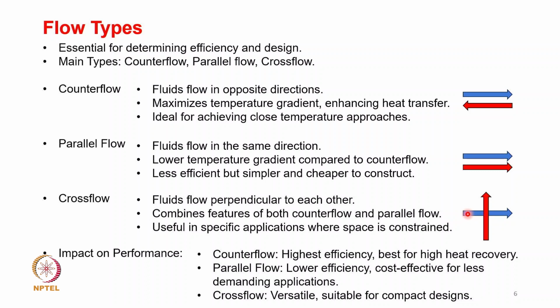The advantage of cross flow is that it combines the features of both counter flow and parallel flow. It is more difficult to achieve, but if your space is constrained, because you need to install your heat exchanger equipment at a particular location where you have a constraint of space, I think cross flow is a better choice.